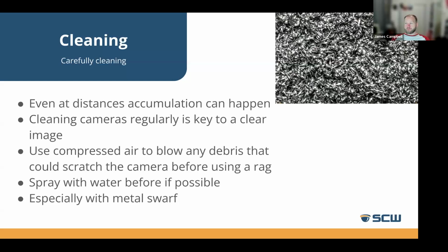And one of the things I would recommend with cleaning it, and I know we have some resources as well to go into more detail on this, but depending on what you have in the air, right? So I know we have some of them that have metal swarf, those little scrap pieces we see here in the corner, and those can eventually just build up on the camera. And so one of the things we've recommended is when they go to clean it, grab a compressed air can and blow the camera off so that there's none of that metal swarf on it before they actually go and use a microfiber cloth or anything like that.